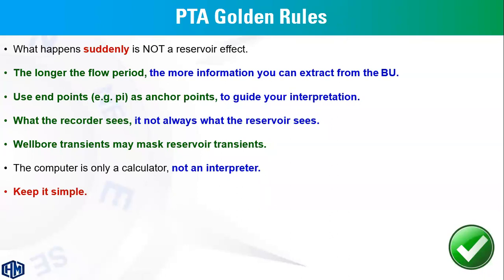The wellbore transients may mask the reservoir transient. The software or the computer is only a calculator. In this case, you have to get a consistent match because you are the interpreter. And finally, start well testing using simple models and add more details step by step.